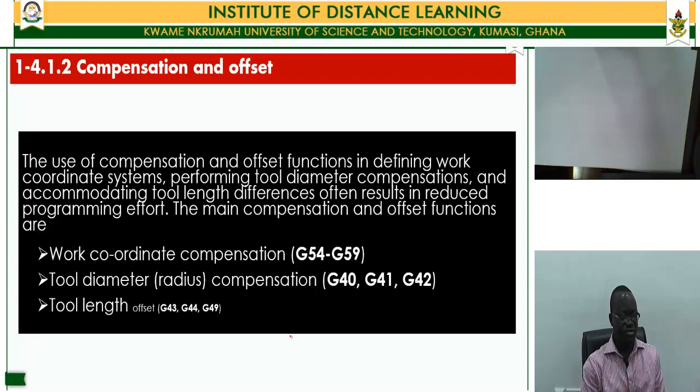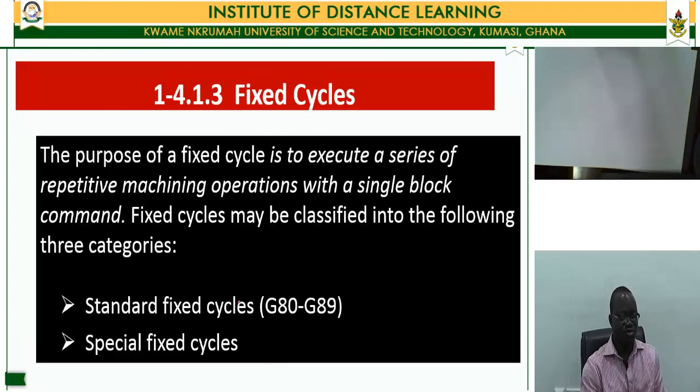and getting the defined geometry machined. Or we can do accommodation for tool length differences when you have a situation where you have to change to a new tool and the length of the tools are different. When that happens, it helps to reduce the programming effort.